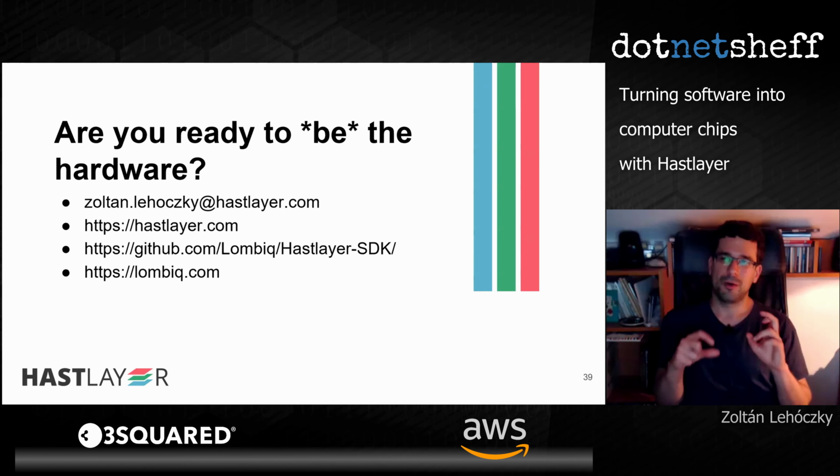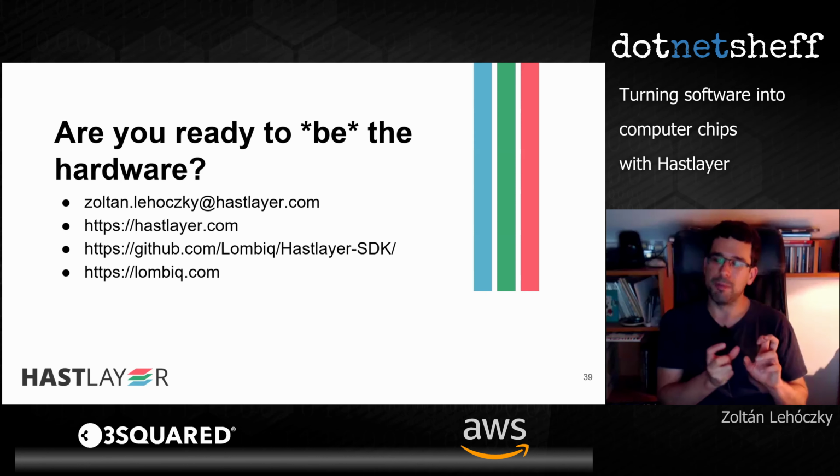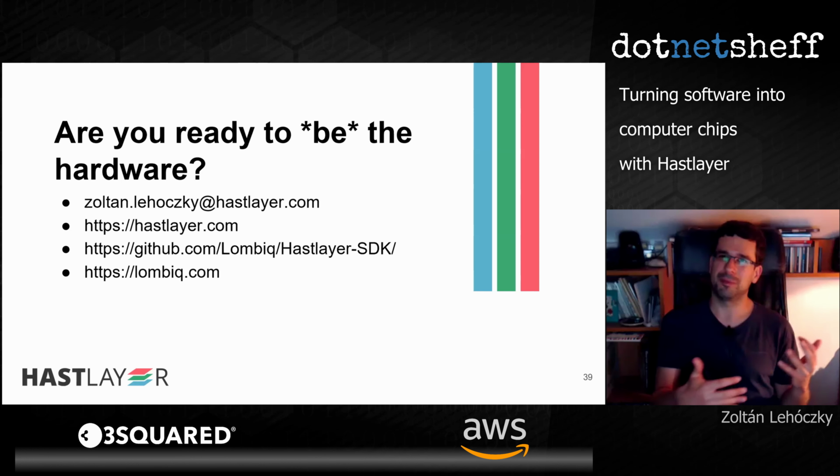We are wiring buses or little pieces of memory into the hardware that will represent the data that object contains. So looking at it that way, we don't actually need memory management, since for almost everything we are not using memory. We are using the hardware fabric, so to say, on the FPGA.